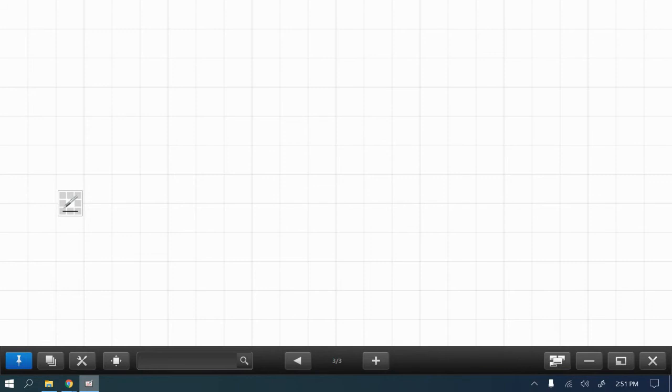So full depth asphalt concrete, I'm going to be looking at the first chart, and you have one for full depth asphalt concrete. The second one in the column is asphalt concrete surface. The third column is plant mix surface using liquid asphalt. And then the last one would be asphalt surface treatment. So it said full depth asphalt concrete, so I'm looking in the very first column.